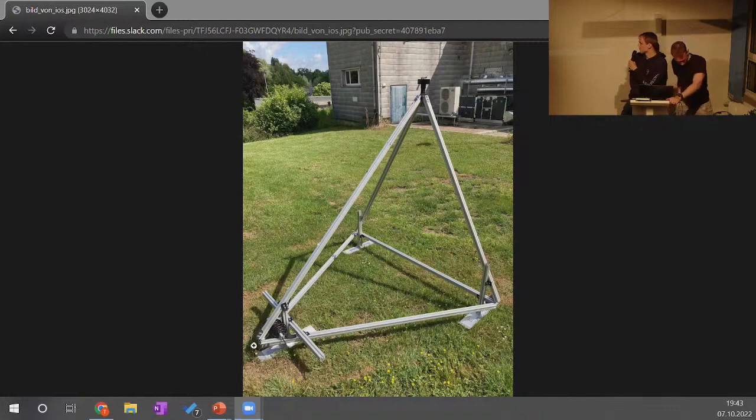On the front we attached the winch, which would normally be used to pull glider planes, and on the back there is a load cell and the parachute, so we can drag it down the landing or starting strip for the glider planes and get our data this way. I think it's a really nice design that the STAR team came up with, and we are also using it for the Aquila rocket to verify our parachutes.